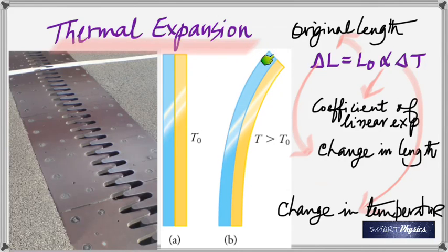You see that? And then it begins to cool. As it begins to cool, what happens? It gets straight, and then it touches. Again, the current flows, gets hot. That's it. Anything that is automatically switching on and off basically uses this. There are other systems, magnetic relays and all that, but this is basically what you use in a refrigerator.